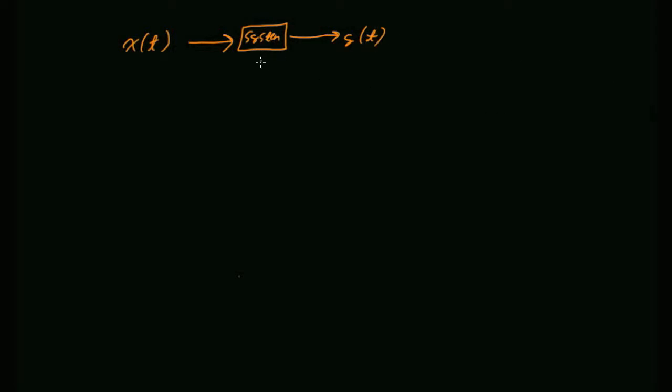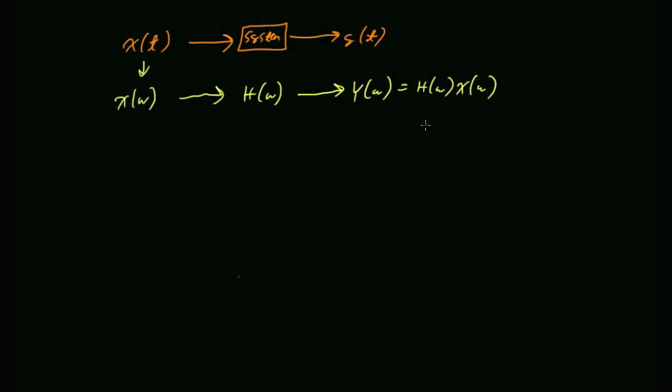And that one option was convert your input signal into the frequency domain, multiply it by the system transfer function, and that will give you the Fourier transform of your output. Okay, so that's cool. That works. Now we have to look at the other avenue. That was a frequency-based approach to finding your solution. Today we're going to examine the time-based approach to estimating your system output.